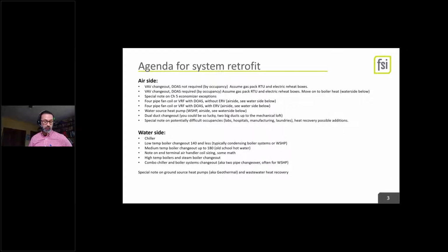In Seattle projects, we've had to replace the electrical service twice now, and it was less than 2% of the construction cost, both times, 2%. So it's a pretty modest cost compared to the whole. Those are major building retrofits, beyond a TI. But still, it's not a giant portion of the work. So we'll see how much that actually limits the Washington version, or how much heat pump we can actually squeeze in, knowing that if buildings already had AC, they might already have enough provision for heat pumps, particularly as they get better at the low temperature.